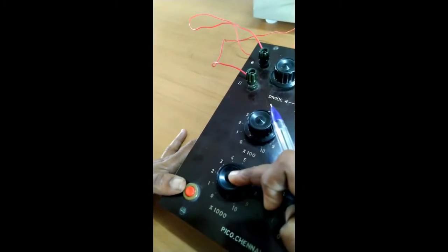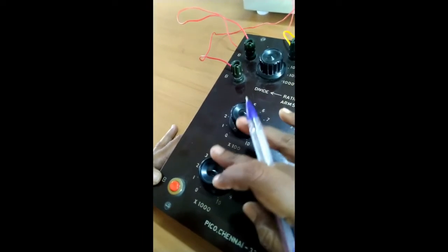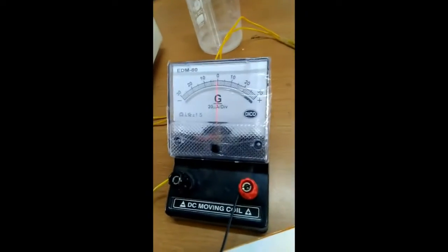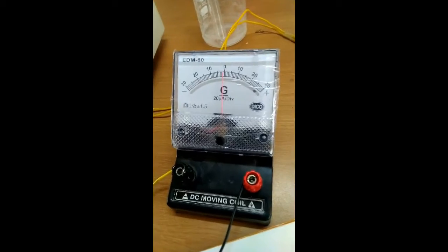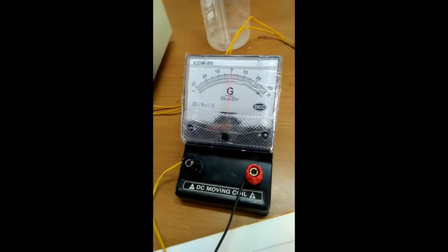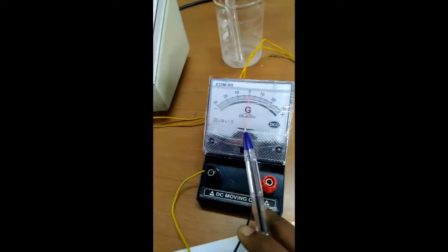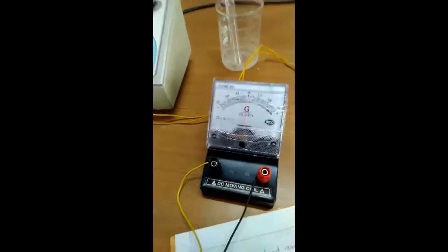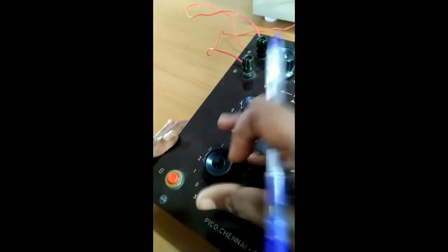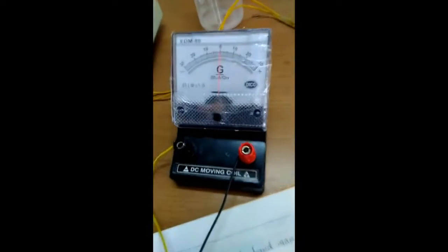Now the resistance in the variable resistance is equal to 1000. Now give a momentary press to the keys and check where the deflection is. See, it is slightly moving towards the left, right? So what we can do again is, as long as this deflection is towards one side, you have to increment the dial, right? Now let us keep it at 2000 and give a momentary kick.